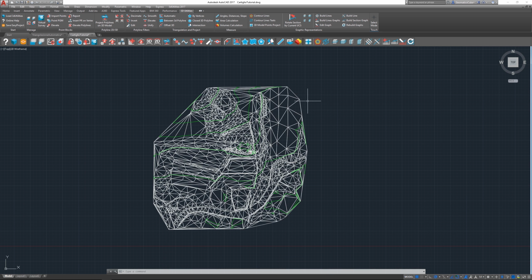This is conceptually very similar to the contour lines command, but it has the advantage of letting me choose where to start, from what elevation to start the sectioning, and it's useful when you need to check the formations of a certain terrain, for example.